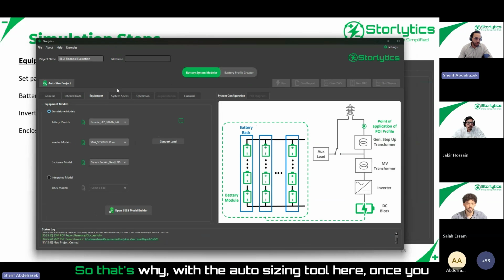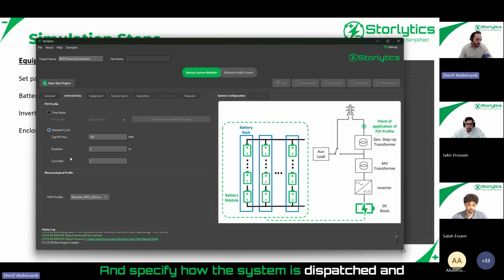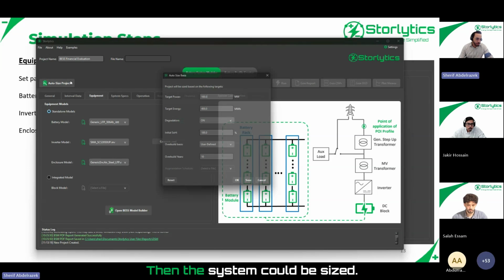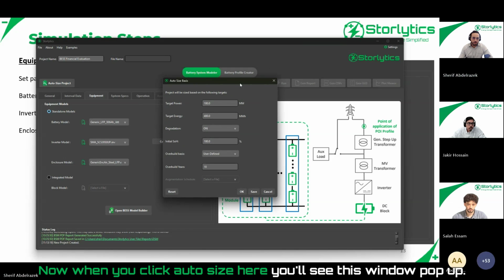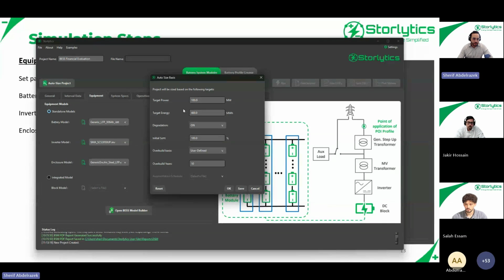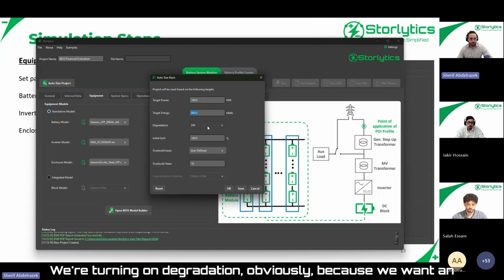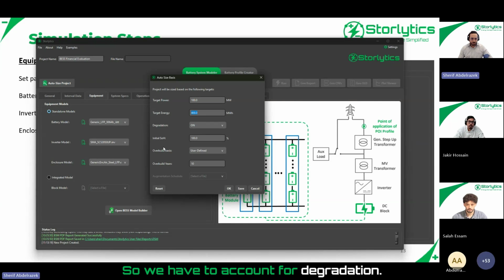All right, so that's why with the auto sizing tool here, once you specify the conditions under the general tab and specify how the system is dispatched and where it's located and the equipment you're using, then the system could be sized. Now, when you click auto size here, you'll see this window pop up. It'll show you basically a summary of the inputs you have. So we are designing for a 100 megawatt project, 400 megawatt hours. We're turning on degradation, obviously, because we want an accurate representation of the estimated cost of the project. So we have to account for degradation.